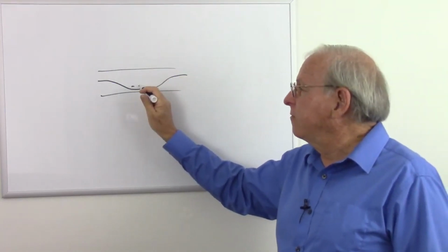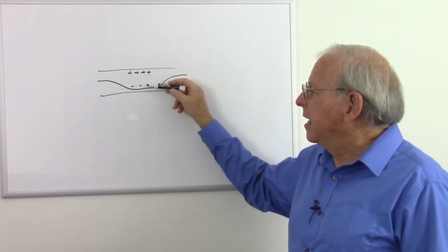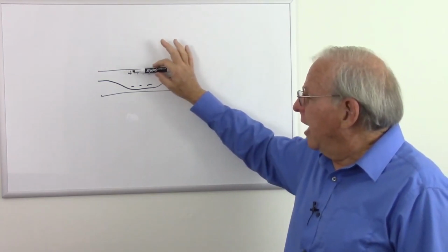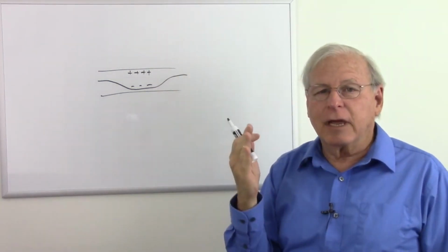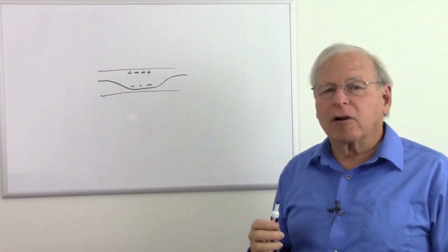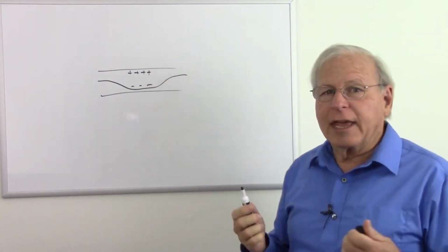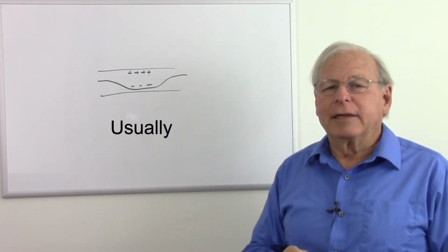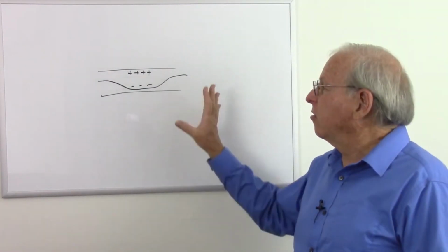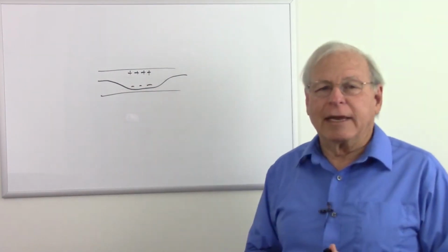We get a negative charge on this side and a positive charge on that side, or should I say a negative potential and a positive potential. So there is a slight voltage across a conductor that has a magnetic field around it and moving electrons. And once again, that's called the Hall effect. And there are solid-state devices that take advantage of this called Hall effect sensors. They look pretty much like a small signal transistor, but you look at the spec sheet to see exactly how to use them, but they can sense magnetic fields. So that's just a solid-state device, with no moving parts, that can sense magnetic fields.